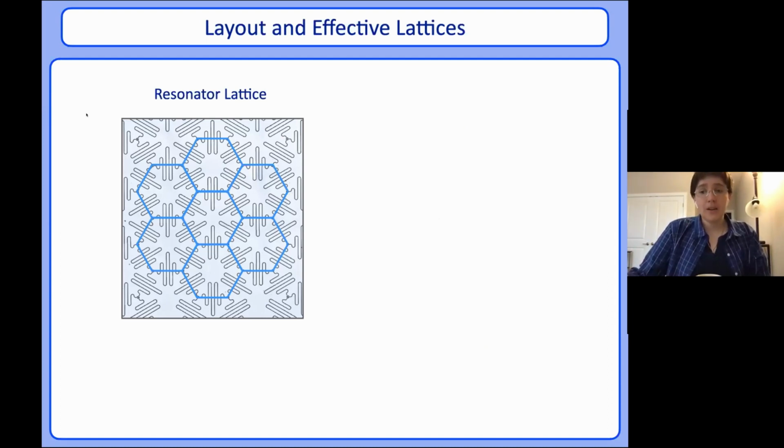And so if we zoom in on a lattice device, now let's look at a Euclidean one for simplicity, and we try to see what sort of lattice is going on here, then your eye probably picked out this honeycomb lattice that I've highlighted. But I have lied to you, because what I have done is I've implicitly put the lattice sites on the coupling capacitors and the hopping matrix elements along each of the resonators.